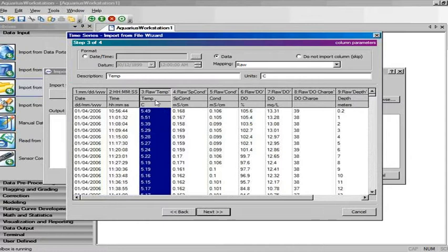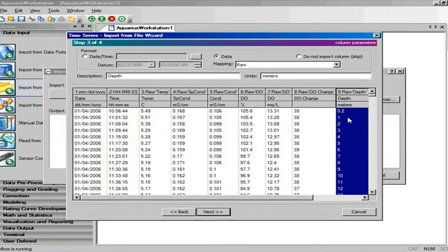Now all of our data columns are actually coming out correctly just because of the way the file is formatted. The two lines above where the data actually starts are where we're getting the description and units from. And we can see here our last column is actually our depth column. You can see how it goes down and it eventually tops out at 14.6 meters, and then we get the next profile starting about a week later. So there's a significant jump in the timestamp here. And you can see we don't have evenly sampled data as we went down. It was just when the sonde was told to record at that specific depth.